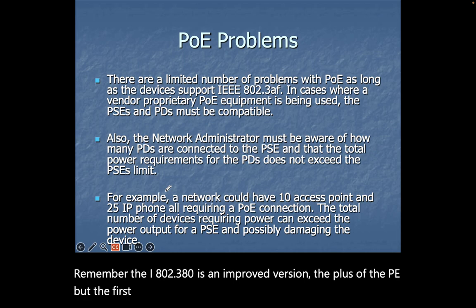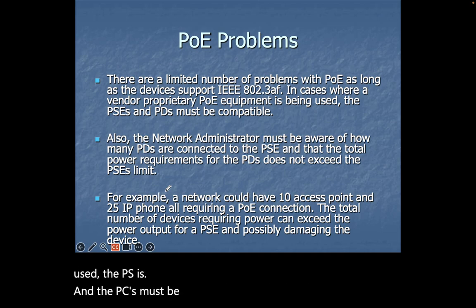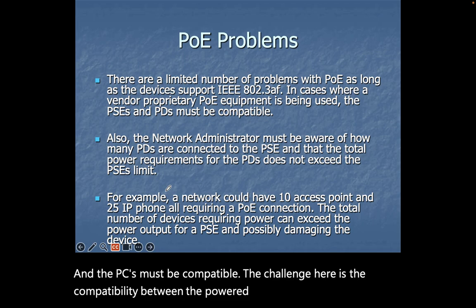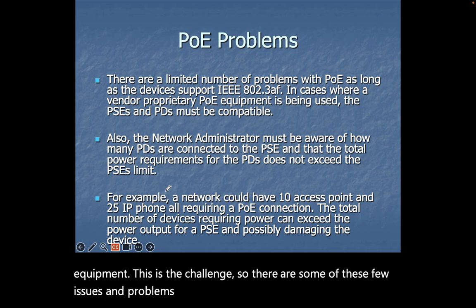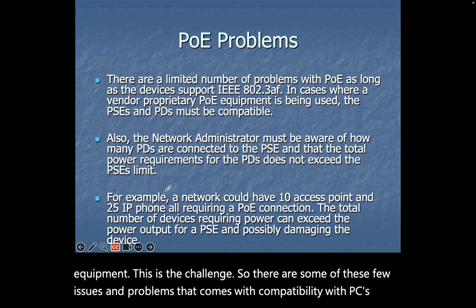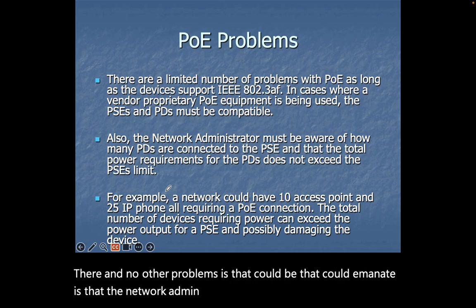But the first one comes with a number of challenges. In cases where vendor proprietary PoE equipment is being used, the PSEs and the PDs must be compatible. The challenge here is the compatibility between the powered devices and the power source equipment. So there are a few issues and problems that come with compatibility between PDs and PSEs.